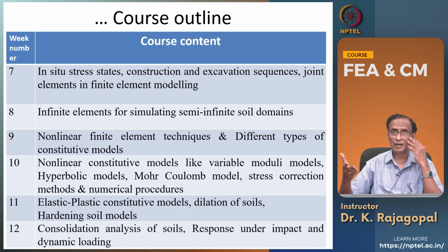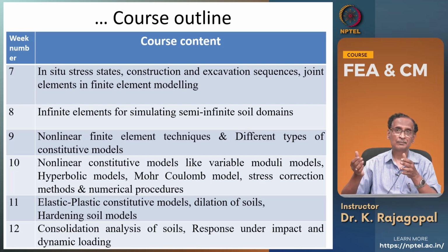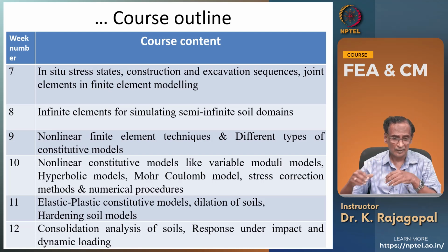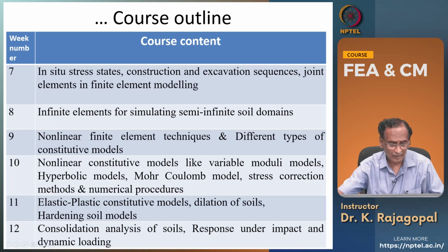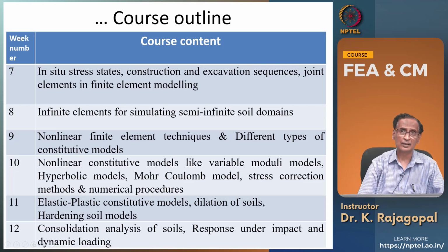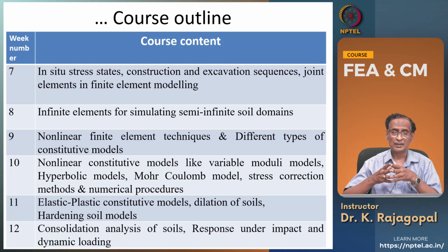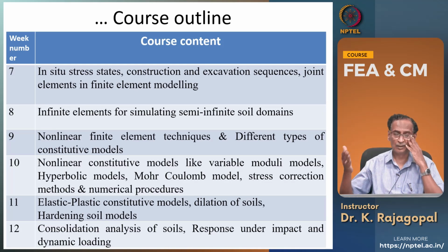But with soil, we know that even if you apply some shear strain, like for example in our direct shear box test, we could get some volume expansion, especially when you have a dense sand or highly angular soil particles. Then we need to have some hardening soil models which differentiate between the loading and unloading paths and so on.